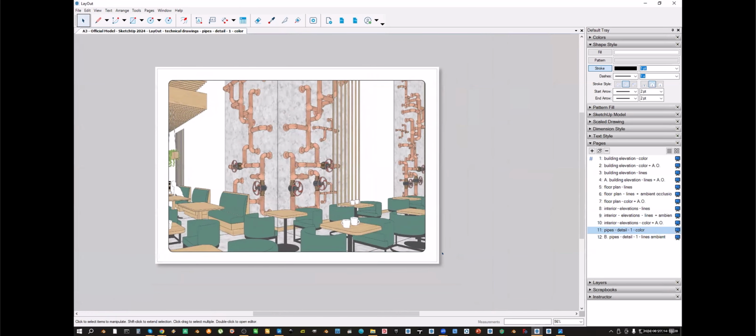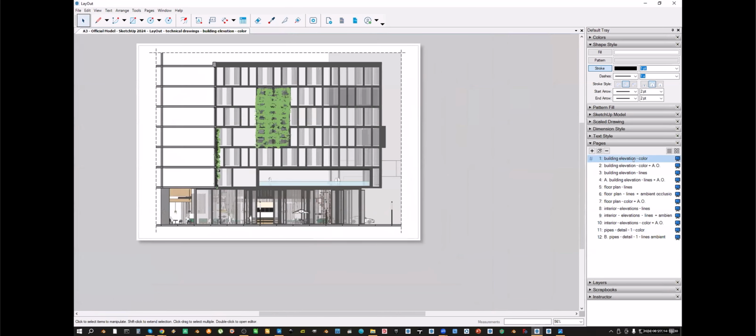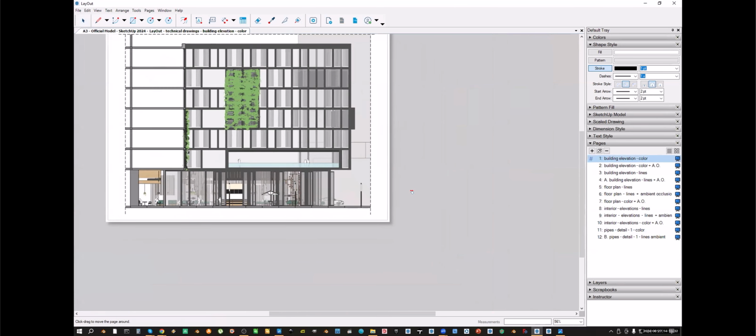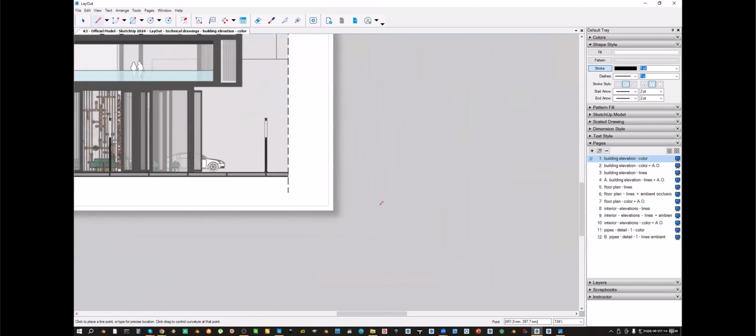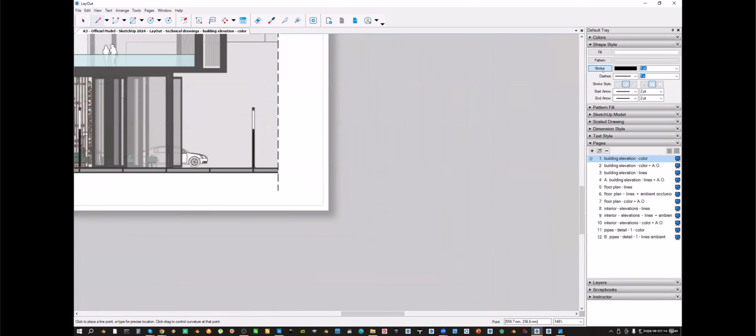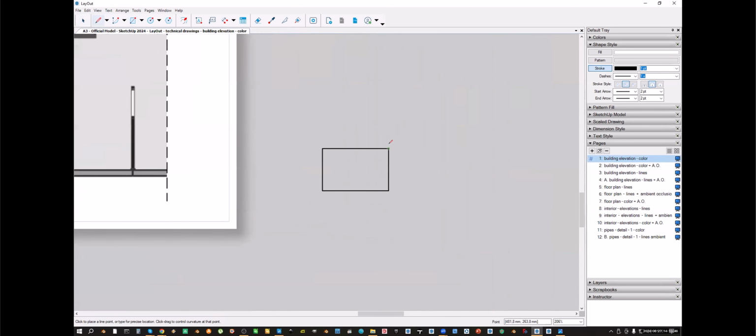So this is one feature. The second feature is snapping. Once we want to draw something in LayOut, everyone knows that the old snapping method was a little bit tedious, but in this case, it's working more like in SketchUp. So if you start to draw the line, or let me just add something in, we start drawing the line, we can lock with the arrow left and right the red axis, and with arrow up the green axis.